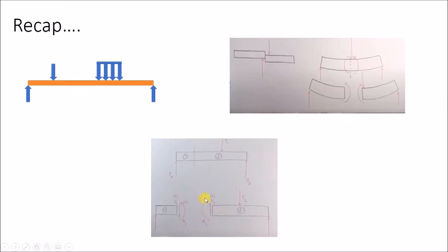and we have two internal bending moment forces shown here. And the two external forces here would be trying to push the beam anti-clockwise. So we have an internal bending moment depicted clockwise because it's trying to resist that external anti-clockwise movement, and likewise over here the upward force would be trying to push this beam in a clockwise direction, so the internal bending moment forces would be trying to resist that in an anti-clockwise direction.